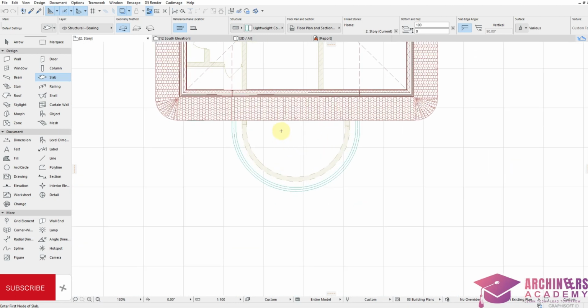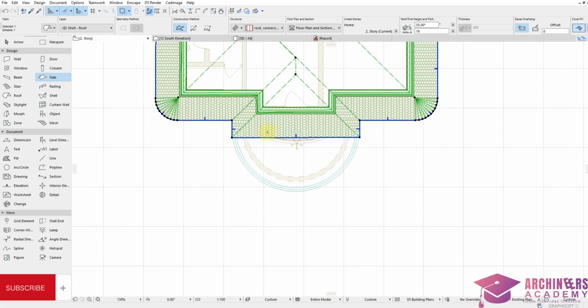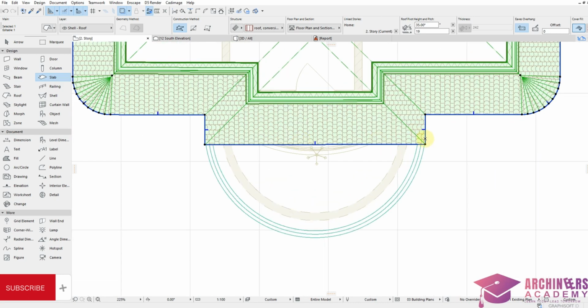Then at the front, what we have to do first is to pick. You just repeat the same process again. Offset it. You pick this edge, then you offset. Click on offset edge. Now bring it a bit forward. Start bringing it a bit forward to where the straight edge is stopped.